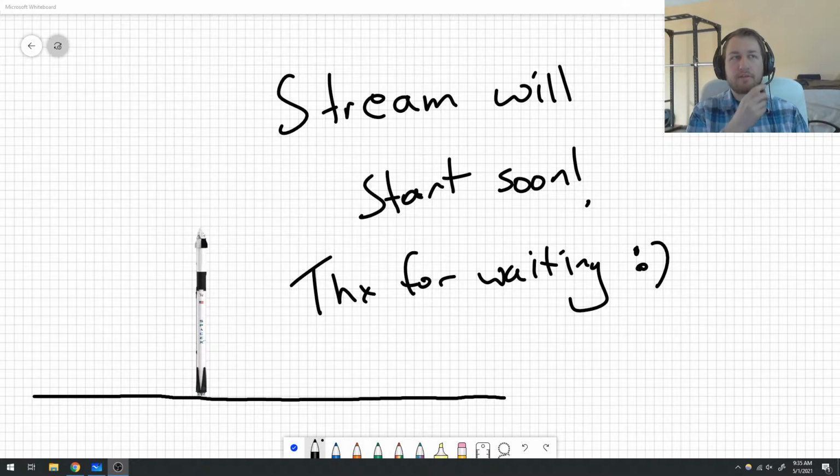Now the GPS is kind of a third part of this whole system that I don't think you really need, but if you're tracking over a longer period of time, especially if it's supersonic flight and your barometer goes crazy, a GPS is helpful. And if you're tracking horizontal distances, like how much your rocket drifts north, south, east, west, then a GPS is definitely needed, and the barometer in that case won't help you.